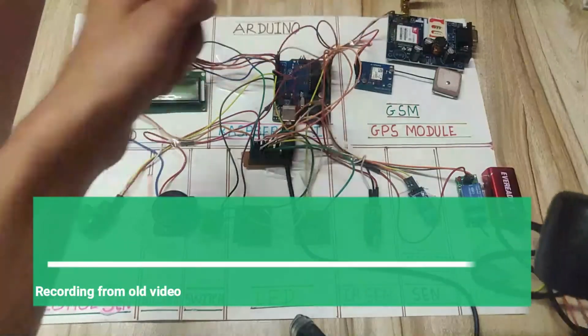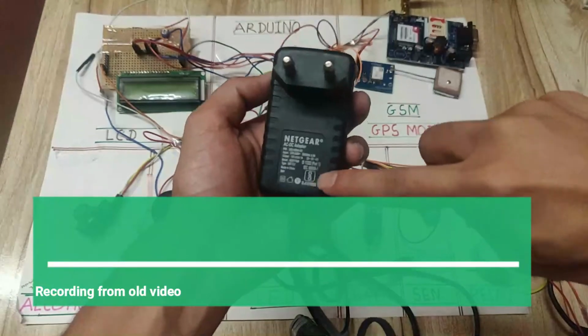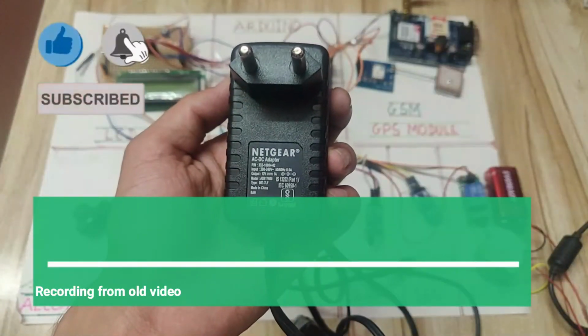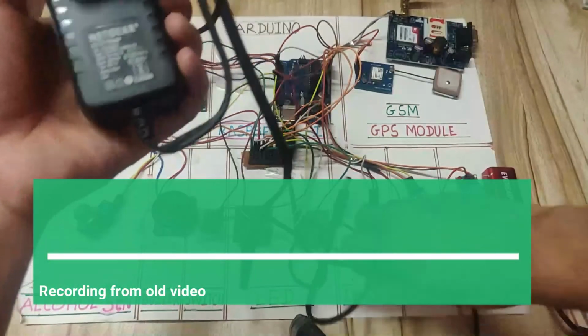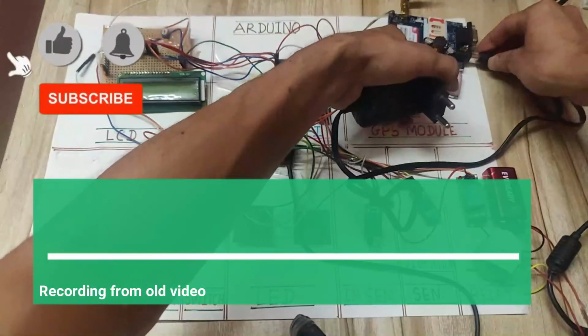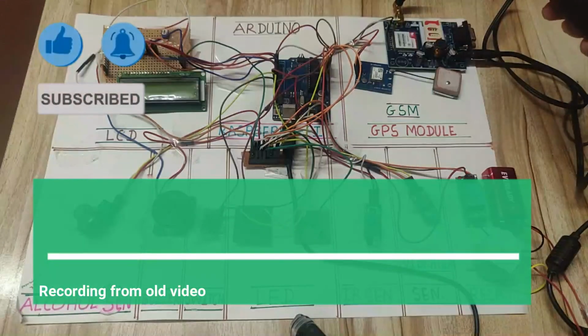This GSM module is SIM 900A, and that SIM 900A requires a 12 volt 1 ampere power supply. So you should buy a 12 volt 1 ampere power adapter externally, give the 12 volt power adapter pin here, and then connect your adapter to your main power supply.